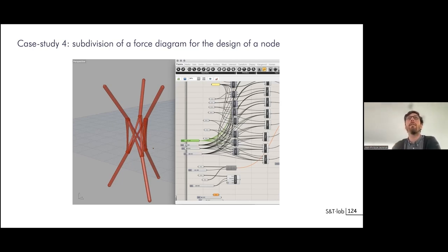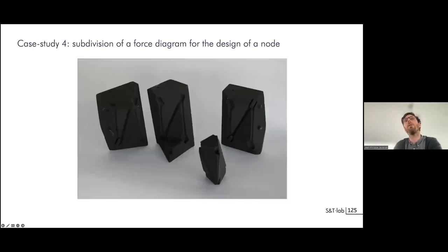So in this case, you can see that through the subdivision, what we got is this same strategy of tripods. So for all the nodes, you have 1, 2, 3 supports that go to 1, 2, 3, okay? Which makes it a bit difficult to build here in the middle if we don't use digital construction. And so the way we did it was aluminum casting into a 3D print mold that you can see here.